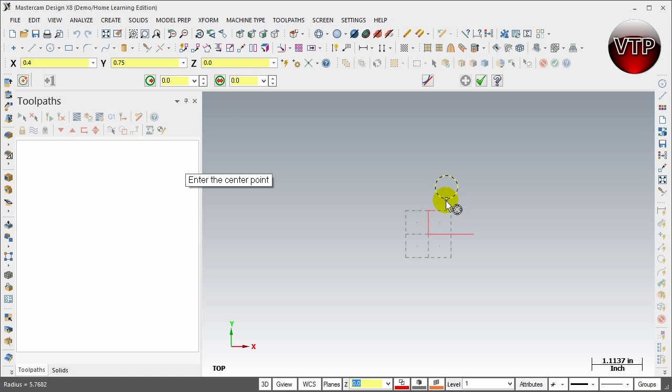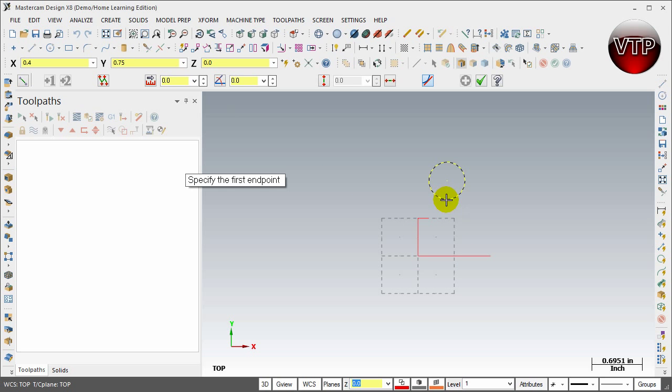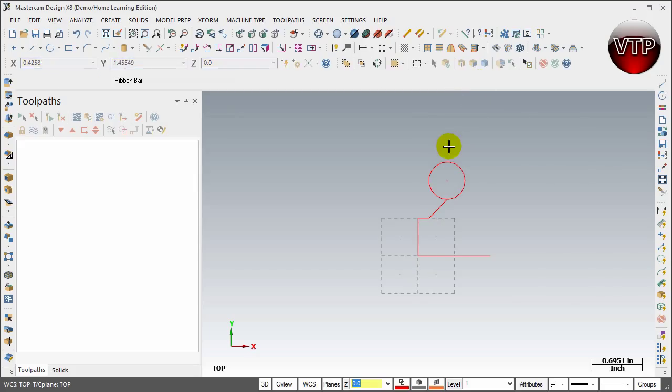So next up, I want to draw a line from here to here. So click on the line again, zoom in, click on the bottom of the circle, and connect it to that line. Click on apply to accept it, and then OK. So there you go. We'll be cutting a piece of this circle a little bit later, but for now, let's keep going with our sketch.